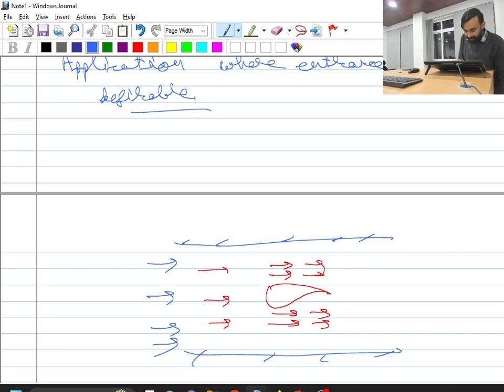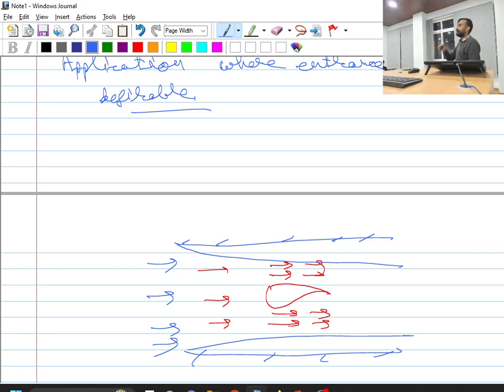If my boundary layer has started growing from this point, I want my boundary layer thickness to be very small so that I have uniform velocity at the core of the flow while it crosses the surface of the airfoil, to make the situation identical to our physical scenario. So this is one important application.